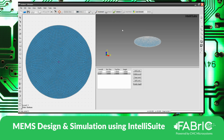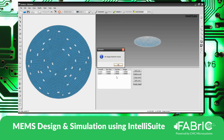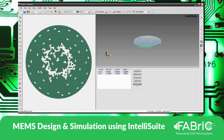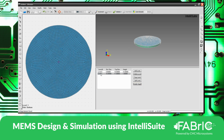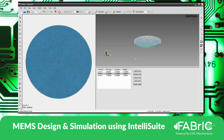I can always check the mesh compatibility. It will show me the current status. So now you may observe that the thickness is by default 1 micrometer. That can be changed to 10 micrometers. And we don't see a gap. So introduce a gap by adding a new level. Here you can see, click on add a new level. You can see a gap between.